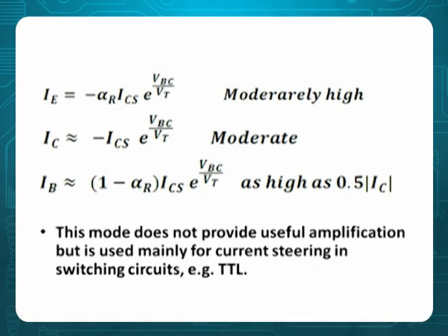So altogether, every time we are seeing what is positive value, what is negative value. If it is positive voltage across the junction, the exponential is far greater than 1. If the voltage is negative, the exponential is far less than 1. And substitute those in the main equations, get your characteristics and understand.